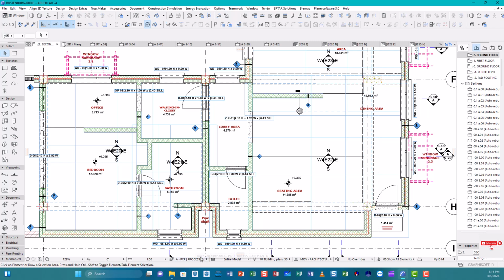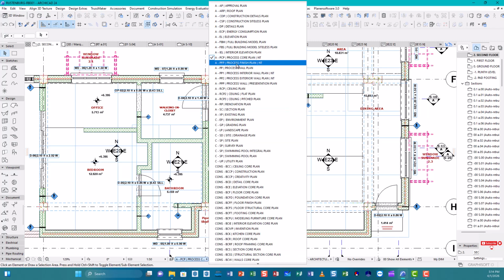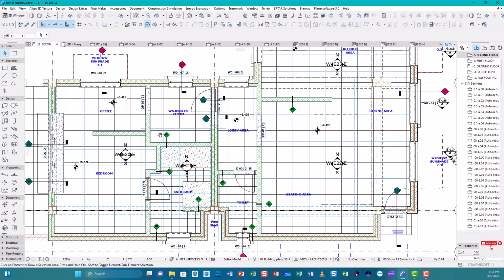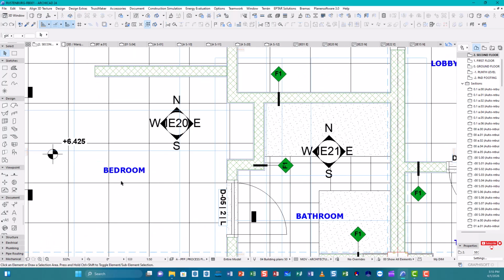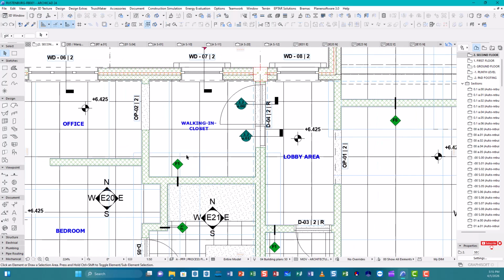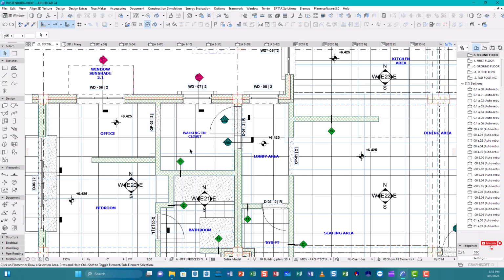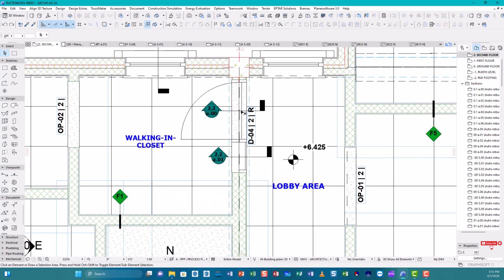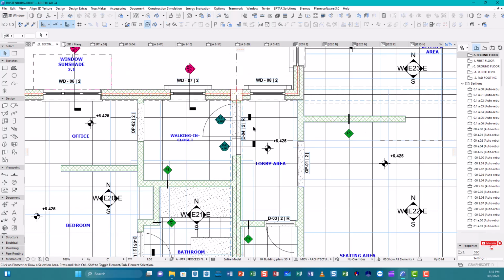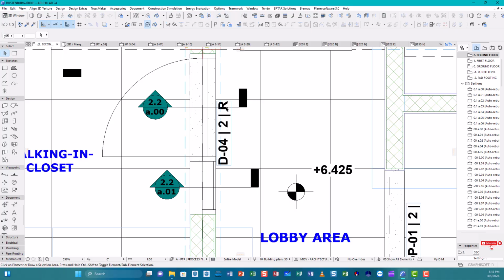So let's keep tagging, let's keep changing our layer combination. Let's go back to this tag which says process finish plan. As I click on it, the environment now shifts around. So this time we're not having any surface area tag there. We're just having now an illustration of our finish floor, and a little structural section is appearing, and once again our opening, I get a new tag.